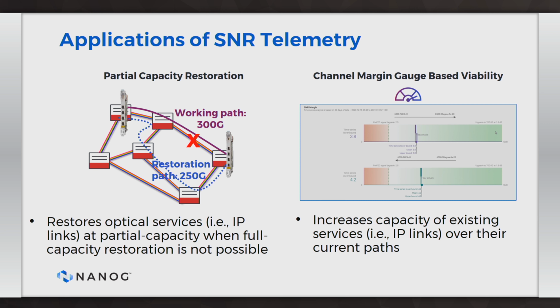Maybe in 6 months or whatever, but there's going to be a failure at some point. You may want to take corrective action. Maybe there is a dirty fiber or a bend someplace, or you just have to reduce the rate. But it tells you the current signal-to-noise ratio as opposed to what you planned in some mathematical model, and then you adjust. Both of these can give you capacity when the IP network needs it.